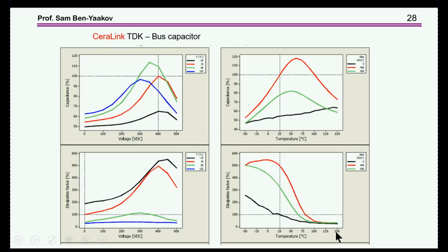So in order to operate a capacitor like that, you have to make sure that it will get to the high temperature. Now, what will happen is that, obviously, at the beginning, if it's at room temperature, because the ESR is high, it'll self-heat, and it'll go to high temperature. But I feel kind of uneasy to work with a capacitor that you have to maintain at 150 degrees, because it also has implications for all the other components on the card.